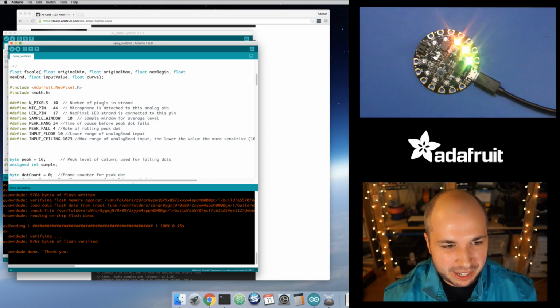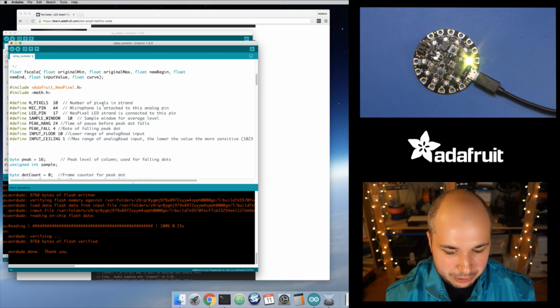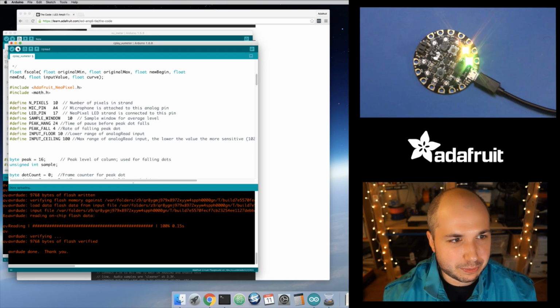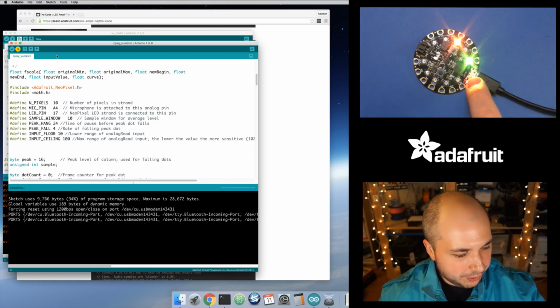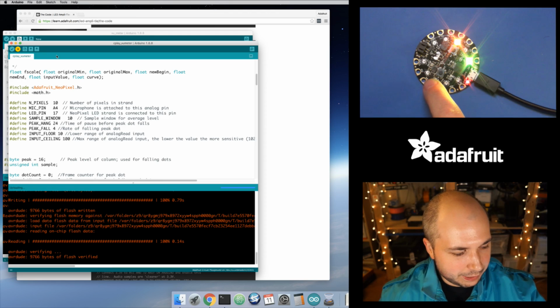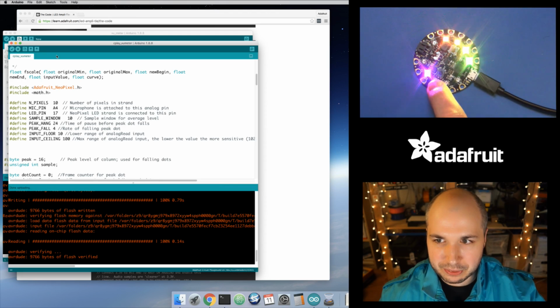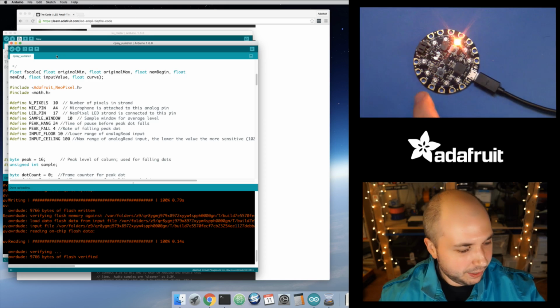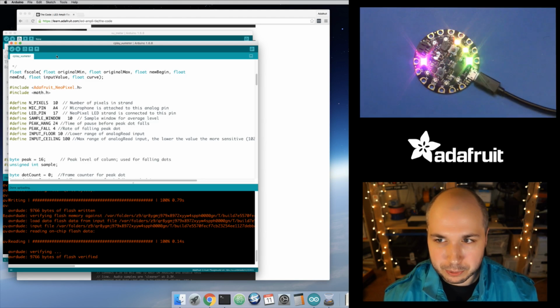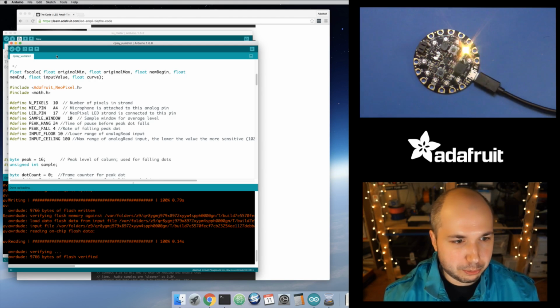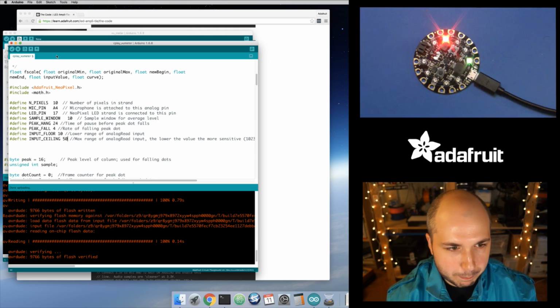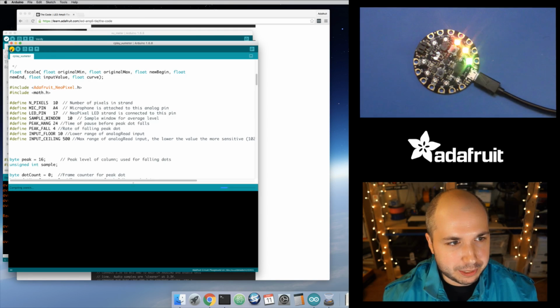So we increased it a lot, and now let's go down. Let's decrease this to like 100 and see what this does. In theory, with my normal talking level we should see it jumping all the way around to here or so. And yeah, if I talk normally, it's going up to almost above LED 5 and 6, and sometimes even higher than that. So that's pretty cool. It's just one little knob here that you can tweak to change the sensitivity. I'll put this back down at 500 so that we get more of a normal level.